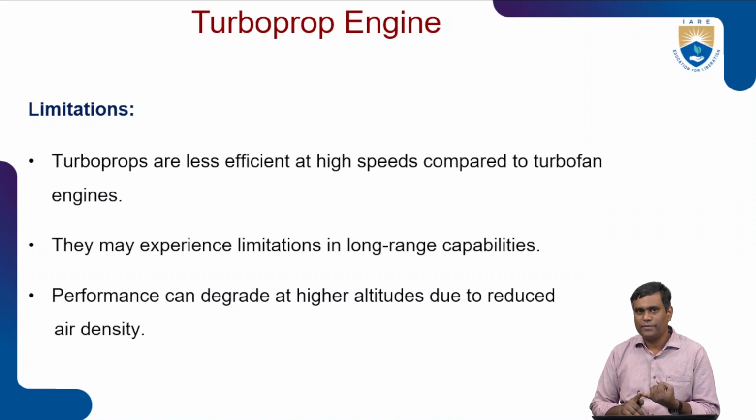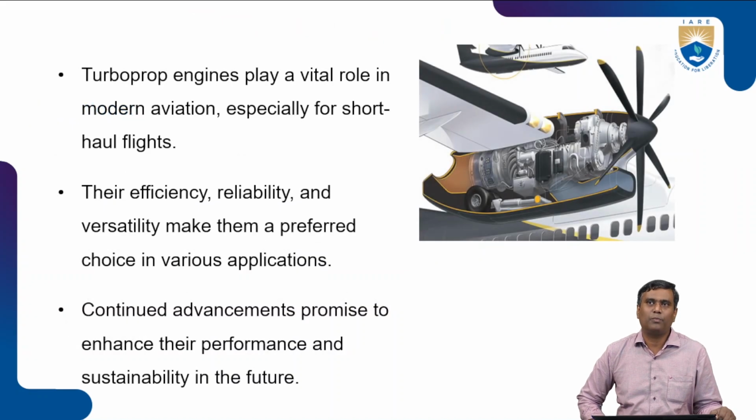So fuel efficient, short takeoff is possible, and in all the way it performs better than turbofan in low speed and low altitude. The limitation will be, as it is propeller driven, as the speed increases, performance will come down, and as the altitude increases, fuel efficiency also will come down. These are the few important points to remember about turboprop.